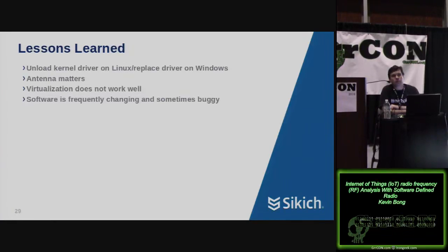The question is, is there software capable of frequency hopping, like your algorithms? The basic stuff that I've used here, like GQRX, I don't believe has any features for that. I'm pretty confident that GNU Radio Companion likely has some modules that can do that type of thing. Software-defined radio can. I haven't gone down that path. A lot of the protocols that I'm using in the up to 1100 megahertz range don't often use that. That's more often used by Bluetooth and things like that at the really high frequencies. From my experience, I don't actually know it that well.